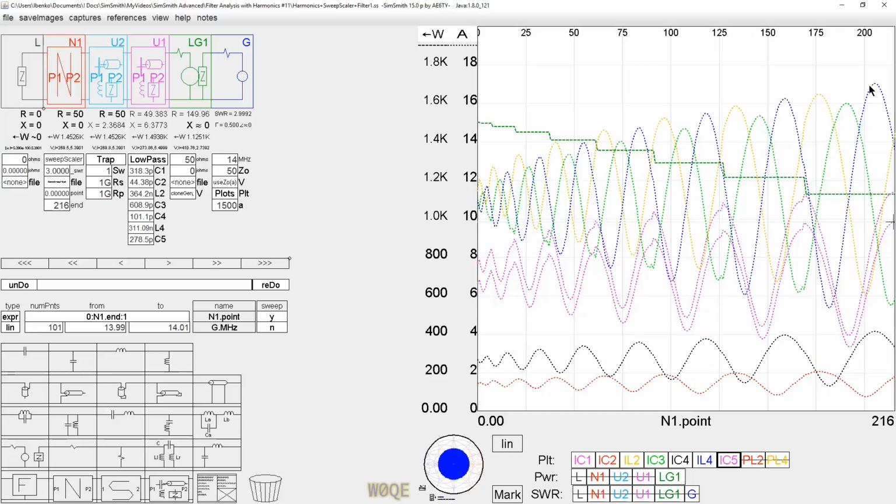And I've had a few people who have come to me and asked me if I would analyze some filters. They weren't all amateur radio. One of them was an ISM band application that was running 15 kW. And doing these analyses is kind of interesting. You get to see that all the parts in the filter certainly are not heated up the same amount. There's no question about that. And they need to be sized accordingly.